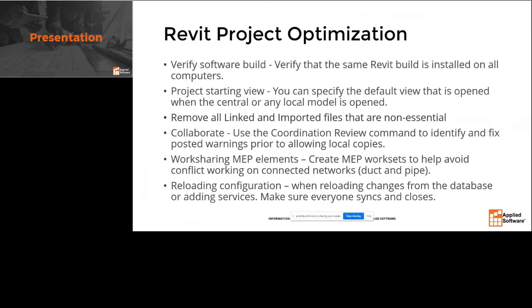What I recently read on the Autodesk website, and I'll show you where I got this information from, is that if you have users on a workshared project that have older hardware that is not up to par with everybody else's, it can lag or reduce performance in the model. So if you have those 2 guys that are not really pushing the project, when they're in it, it starts to bog the project down a little bit. So that might be something to consider if you have teams that are all in-house and you have knowledge of each computer's hardware and system requirements.